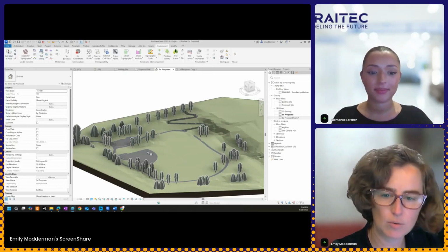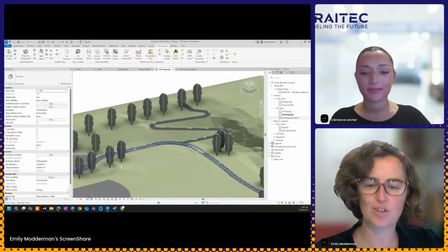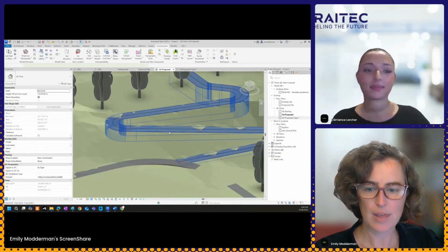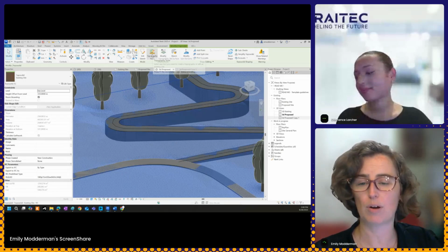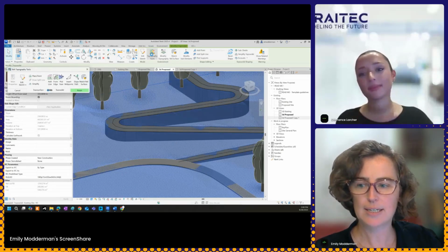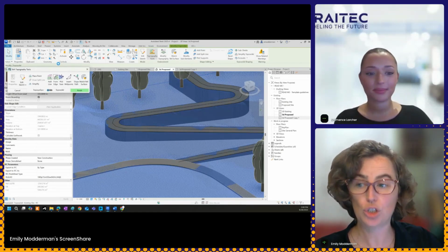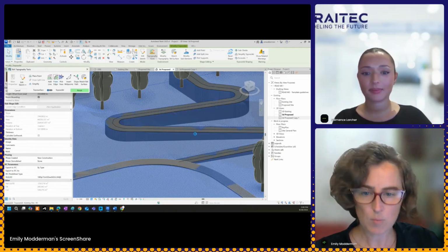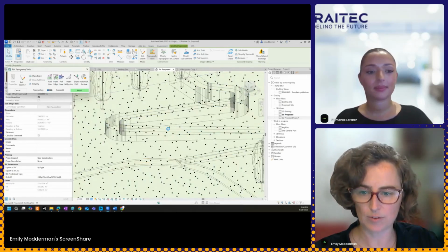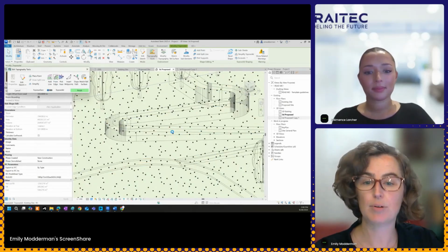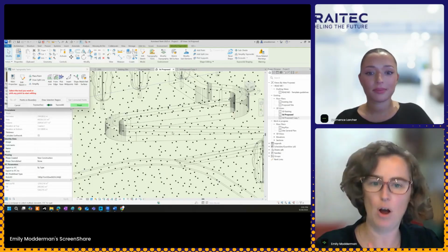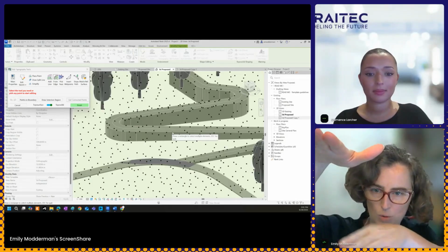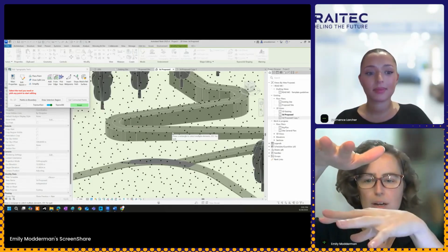Ah, I see. Okay, we'll answer this one because I did ask for more details. I think you're going to go into the topography tools and choose something like from edge. In the same way I selected the edge of one of these surfaces, I'm able then to set a negative or positive offset. So you've got this floating platform and now you've got your slope coming down here and there's nothing, it's just empty.